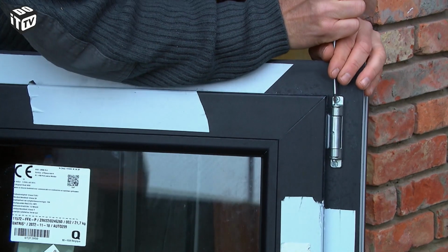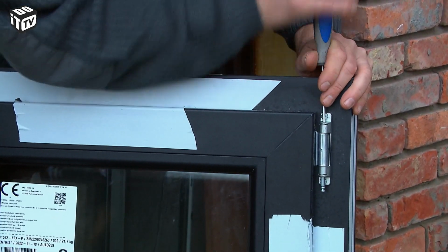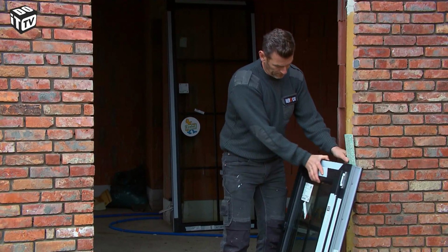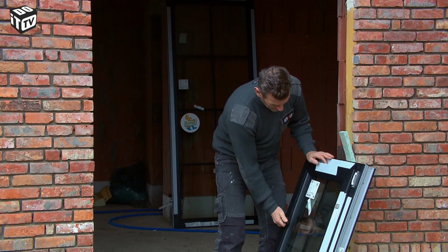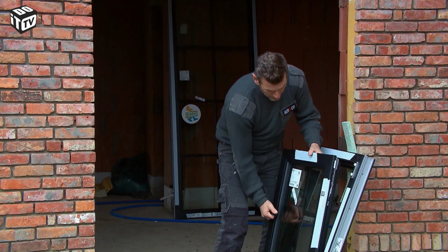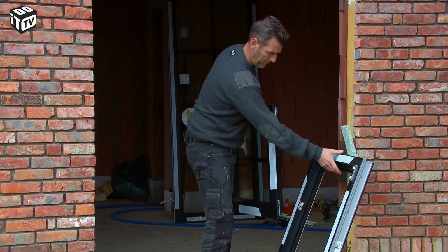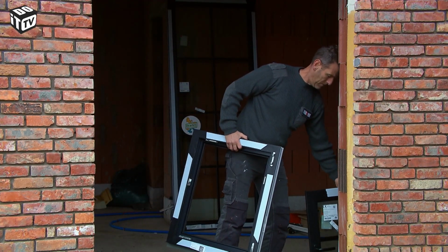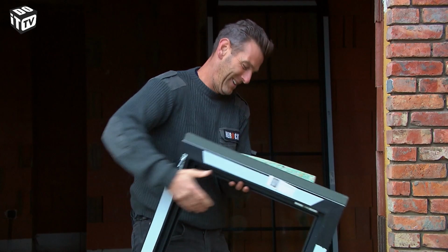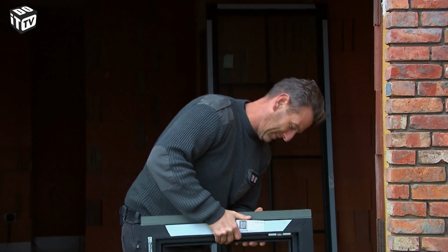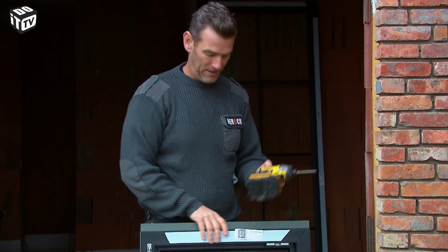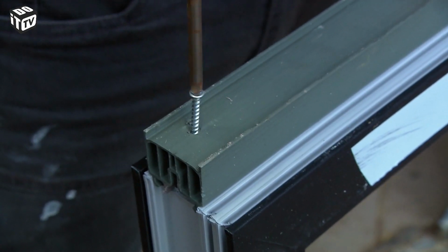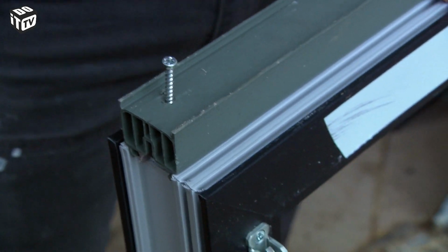Push the pin out of the hinges. This way you can remove the window from the casing. Put it aside. Turn the frame upside down so you can remove the plastic housing at the bottom. This ensured that the window could not get scratched during transport. This was temporarily screwed in place and can therefore be quickly dismantled.